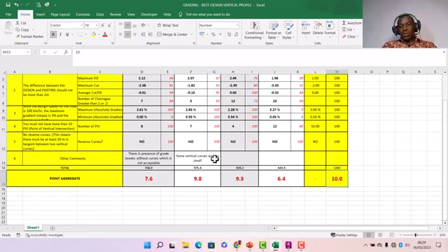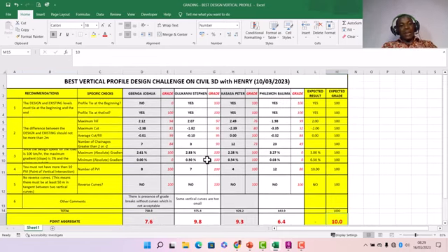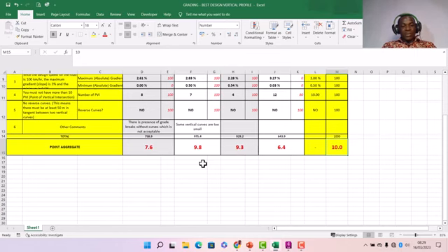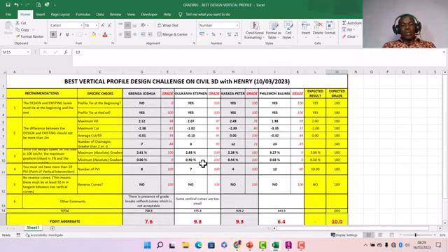It was almost like a grade break. The vertical curve should have at least some good length. Not just because you want to fine-tune your profile, you insert a small curve. No, it will be like a bump on the road when driving. Besides, your code should have even flagged that, if you have some checks. So it's good practice as you are designing.